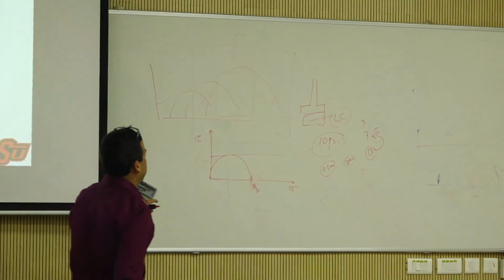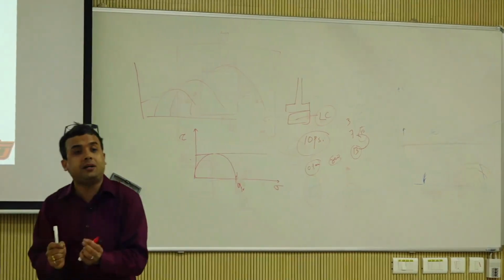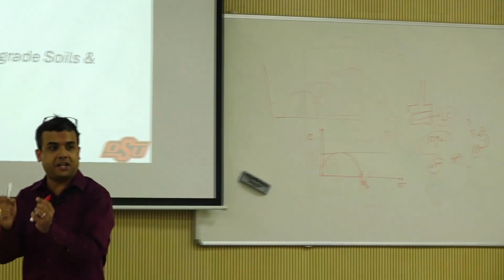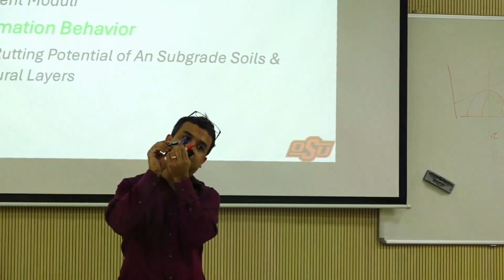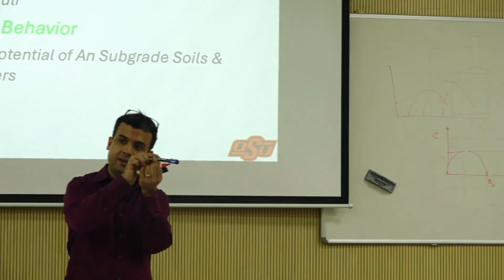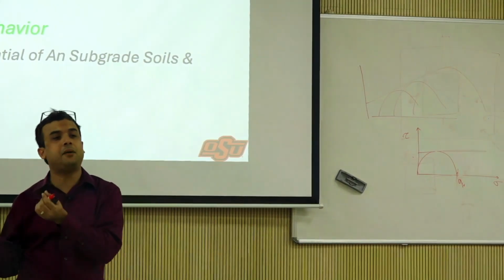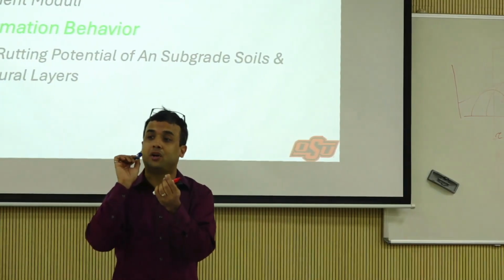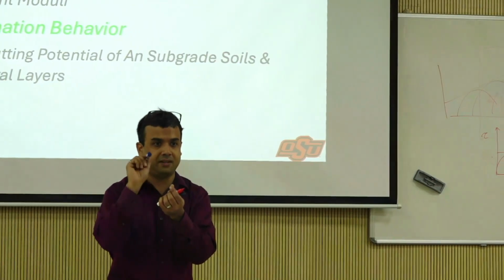In triaxial testing, or shear strength testing, it's called monotonic triaxial testing, because monotonic means you are just pushing it at one given rate. Other than that, resilient modulus and stuff, when we get into that, it's called repeated triaxial testing, because you're going to pulse it.